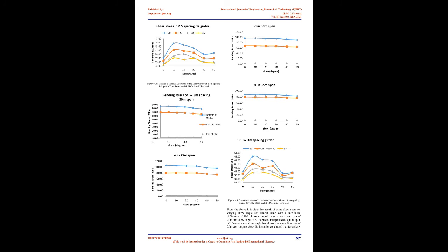In this study, the 70R wheeled vehicle is considered since it produced the maximum moment when compared to other IRC loadings, for spans up to 40 m. The basic configuration of Class 70R and Class A loading is depicted in Figure 3.2 and Figure 3.3, the basic configuration of a Class A train of vehicles. The minimum specified clearance between the outer edge of the wheel and the roadway face of the curb, and the minimum clearance between the outer edges of passing or crossing vehicles on multi-lane bridges, are taken from the codes in accordance with IRC specification. The transverse placement of load is shown in Figure 4.